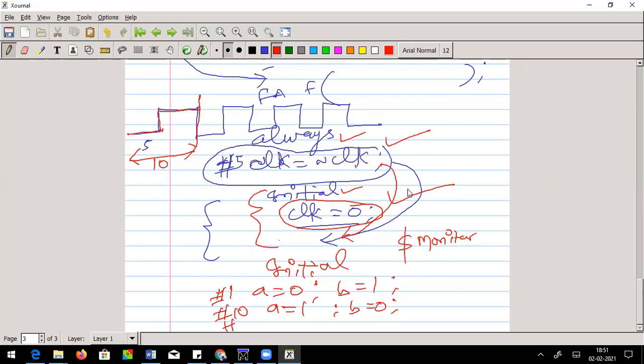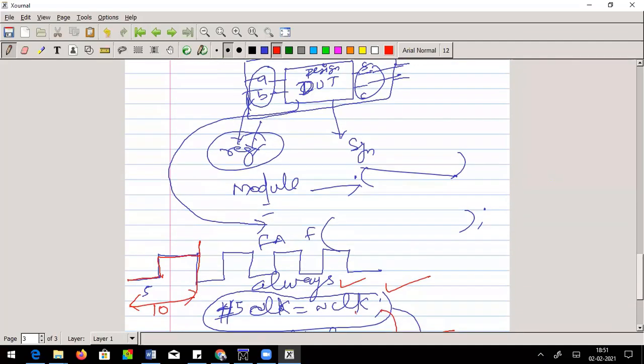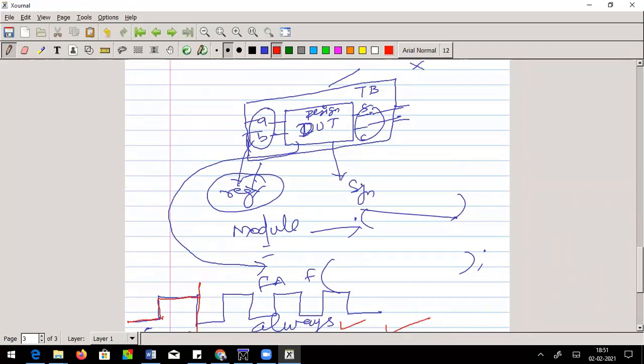That's all. So as such, now we have seen what a test bench is. Basically, a test bench is used to test your design. Apart from that, it doesn't have any role in your design, and it cannot be synthesized. There are some statements specifically used inside the test bench alone, like initial, $display, $monitor, all those things which cannot get synthesized in the design, but will be used only for the design test bench. And you can generate a clock, all those things can be done.